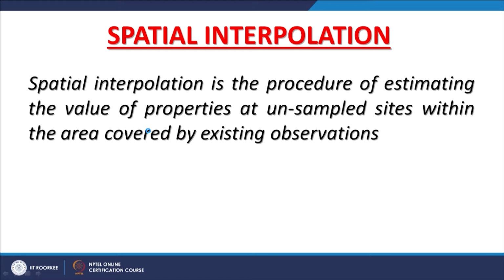As you also know, these contours are interpolated from point data. So in the field, especially while making these survey topo sheets, only the point heights are collected, and then later on the contours are generated. So contours are interpolated from point data. So using that information we can definitely go for